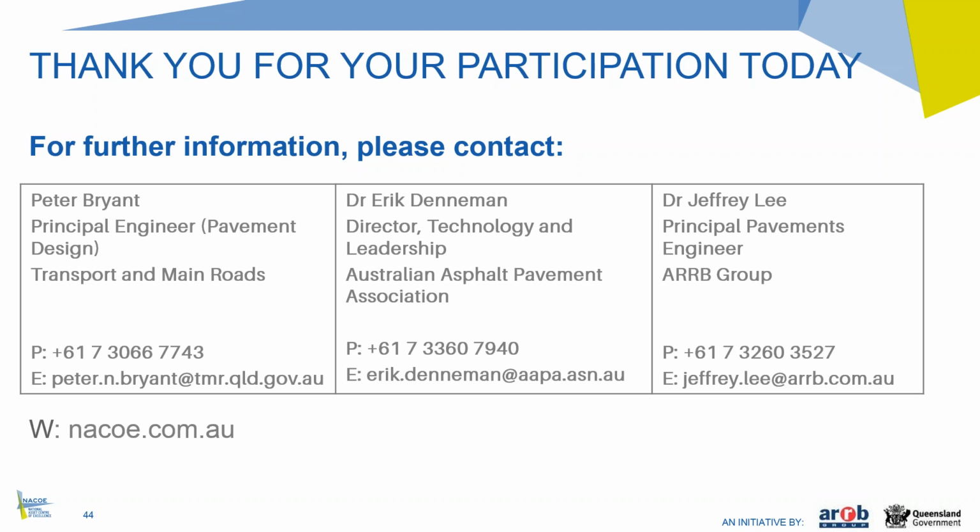Yeah, I can answer that. I think there would be an expectation for the lab to be NATA registered because we require that for any other testing. I don't see why it would be different in this case. The cost of the testing, some rough figures, would probably be in the range of about $20,000 to $25,000 for a single mix. And I think, again, we need to keep in mind the potential savings that can come from optimising mixes, so that 20 to 25,000 is really a very low percentage of a project budget.